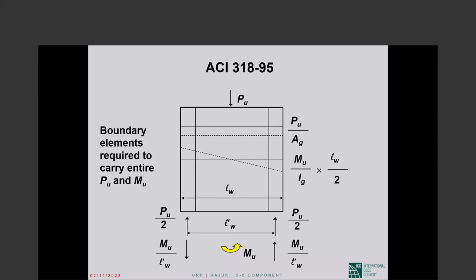So with that long background of where we have been and where we are, let us look at what we had in 1995, which I'm sure is the same as what we had in 1989, which is the way you have been designing shear walls up until now. Okay? So in this procedure, we are supposed to consider the factored axial load tributary to our shear wall.